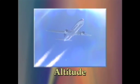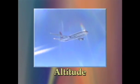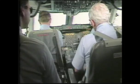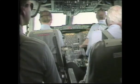Altitude. The greater the altitude when the decompression occurs, the more severe the physiological effects. Physical characteristics of a rapid decompression can cause the pilot operational problems. For example, noise from a decompression can range from a hissing to a very loud explosive sound. Operationally, there can be a disruption in communication.